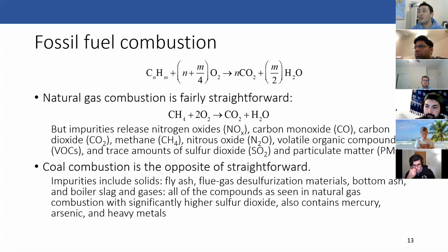So you only want to make that natural gas as pure as is economically efficient, and two, from regulations that are requiring that the combustion process itself is adhering to a specific standard. And so those are going to drive how pure the methane ends up being after the pre-processing step.